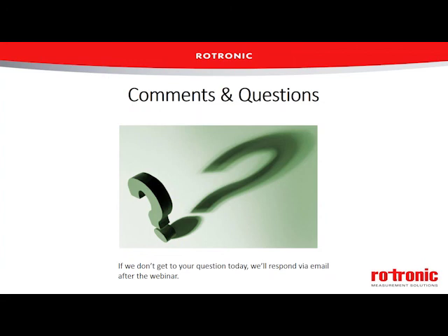Now, I'm assuming here that you're interested in relative humidity. And if that's the case, I would use a capacitive sensor to do that, because the capacitive sensor senses actual relative humidity. So its value will change based on relative humidity, and it won't care if you've got a vacuum that's changing.